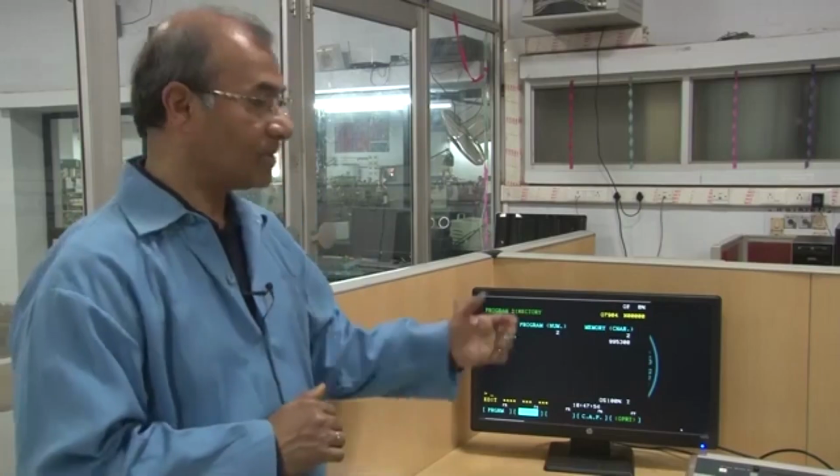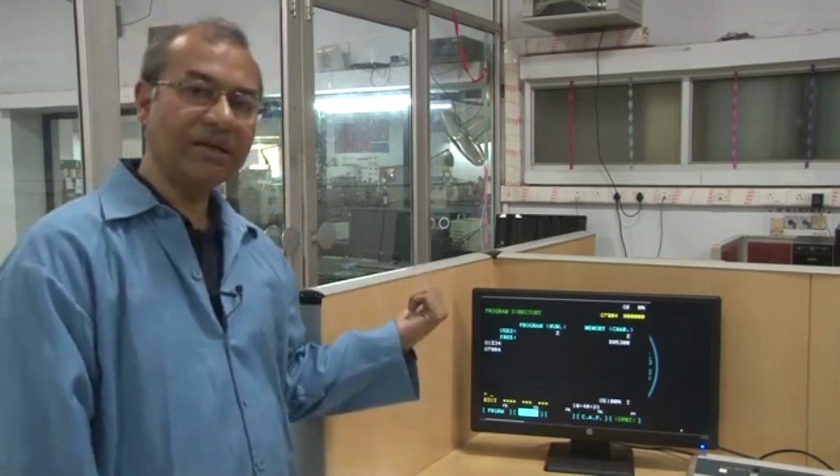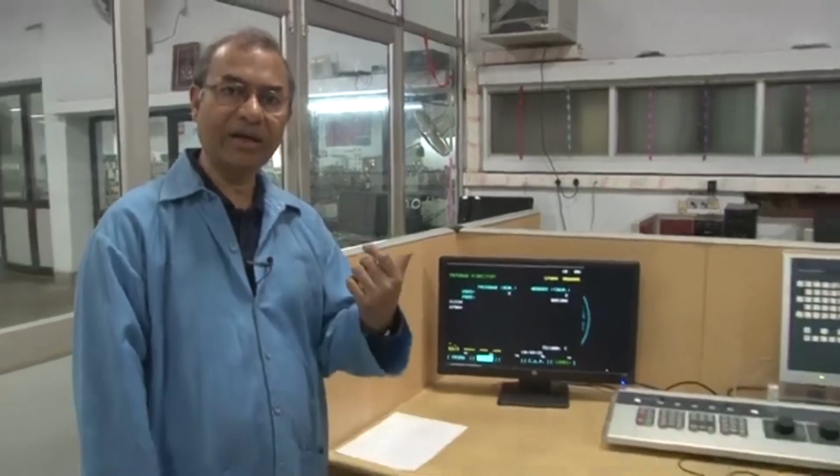And as I told you, after you make the program manually on a piece of paper, that program has to be tested so there is no flaw in the program. That program has to be run through the simulator, and the simulator will show you whether the program is right and the relative movement between the tool and the workpiece goes on without any conflict. After you get the result, only then the program has to be brought to the machine, and the machine will then fabricate the parts. So, this is the simulator, and now we will show you how each of the lines in the program can be made here in the simulator and how that can be executed.